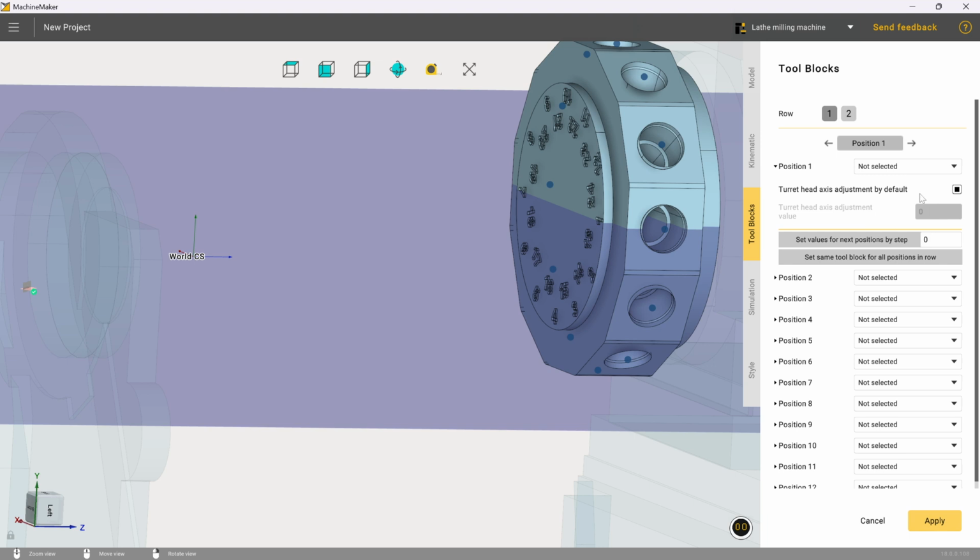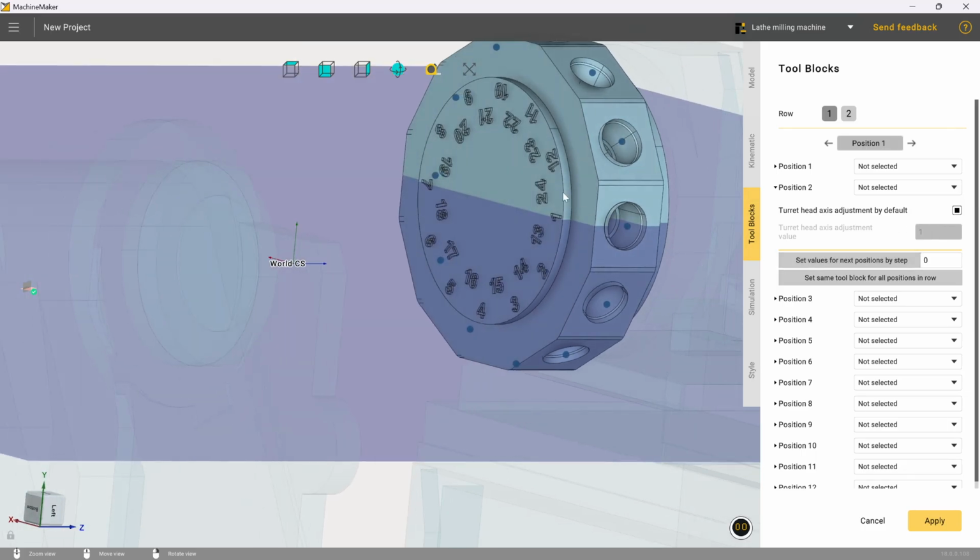So first things first, we are going to go into position 1 here, and we are going to set the values for each of these axis attachment values. So we see in position 1 it's set to 0, set here to 0. Position 2 it's set to 1. Because we have got 2 rows of staggered tools, we're going to change that a bit so that row 1 is the even designations and row 2 is the odd designations, due to the way the offsets here are defined.